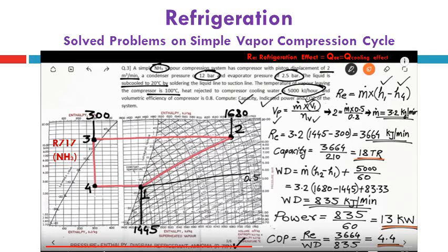Then we will estimate the indicated power of the compressor, listed below. Firstly, we estimate the work of the compressor, the displacement work performed by the compressor, nomenclatured in this solution as WD, referring to displacement work. It is divided into two parts. One part is dedicated to the compression process from H1 to H2 for a certain amount of refrigerant.